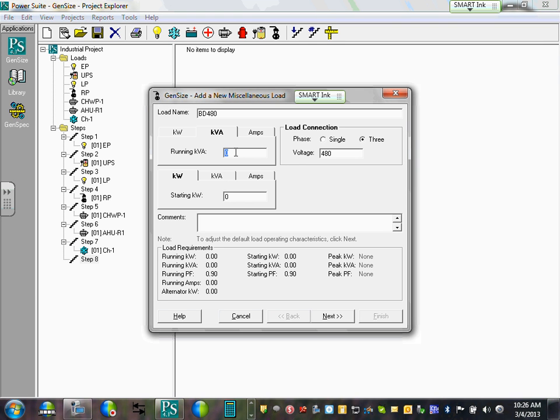Now, can you give me the kVA on the busway, the kVA from your load calc, Aaron, about your busway, the 480. kVA is 1,000. Are you sure? No, that's kVA, sorry, 660. Okay, 660. Starting capability. Now, because it's user defined, guys, they want you to do the starting capability. I'm going to double this. Usually, the starting capability goes from 2 all the way to 6 times. So I'm going to use what's 2 times 666?